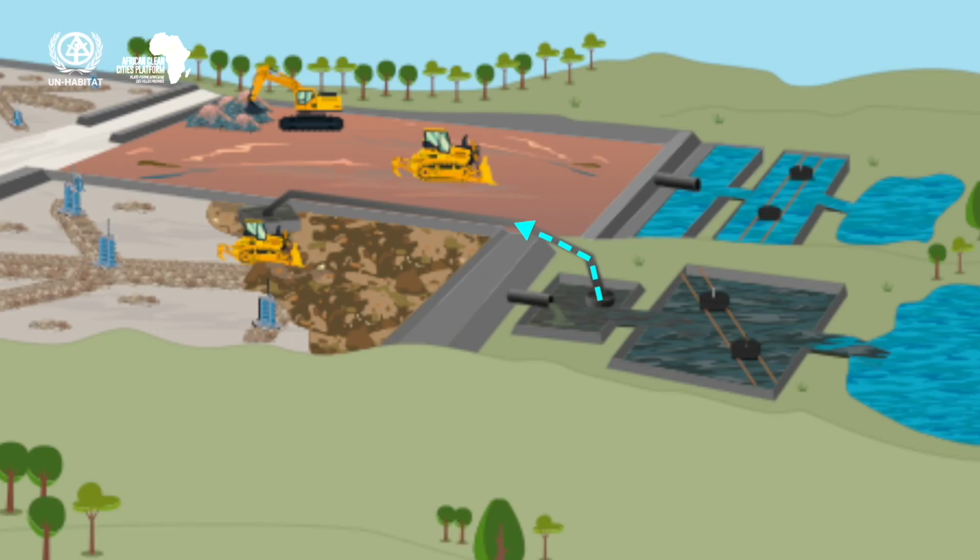However, leachate recirculation is only possible by pumping back the leachate from a leachate treatment pond at lower ground to the top surface of a landfill structure. So do keep in mind that either electricity or fuels are essential to keep the pumping system running. There's also a risk of mechanical failures of the pump. So mechanical engineers must be regularly available to fix problems if they arise.